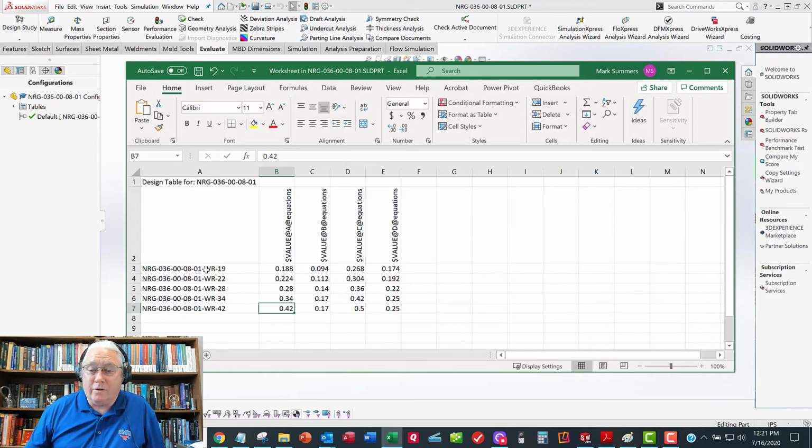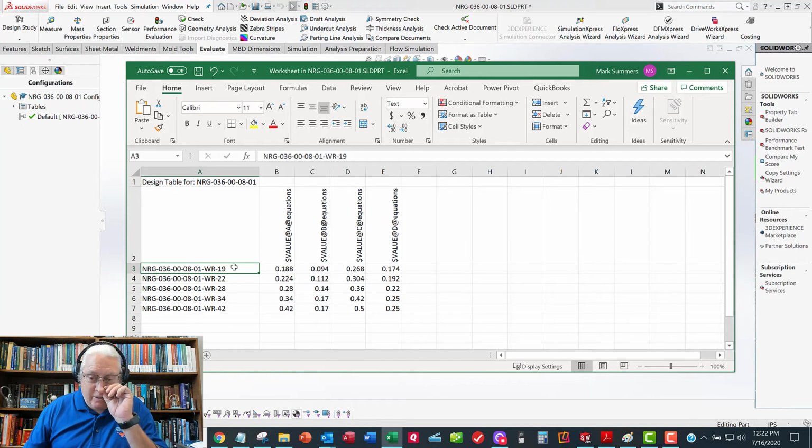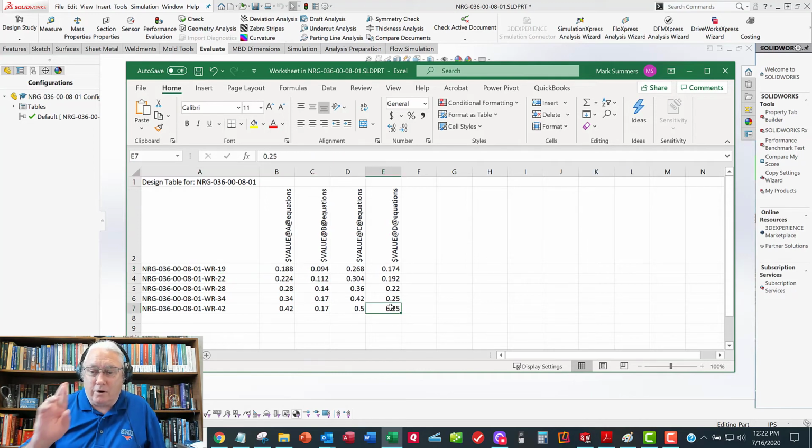So make sure you start this guy here at cell B2. It's going to say first instance when you open this thing up. That's where you put your first instance. You have to remember what you enter here because these are going to be referenced in the assembly model configurations. So if you muck this up, your assembly model is going to be mucked up. At this point, you just cross your fingers, close Excel, and hope that it works.